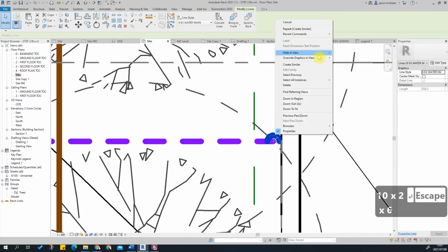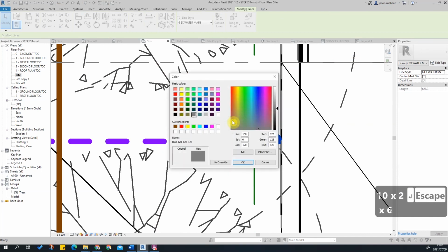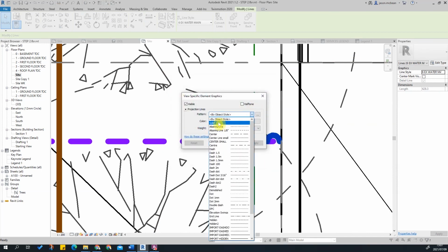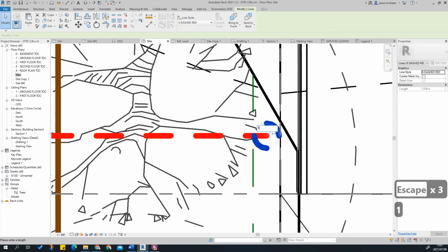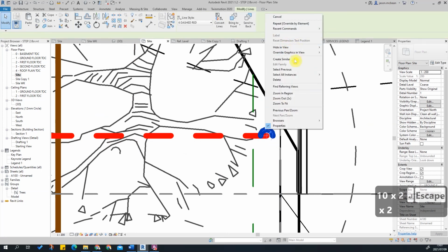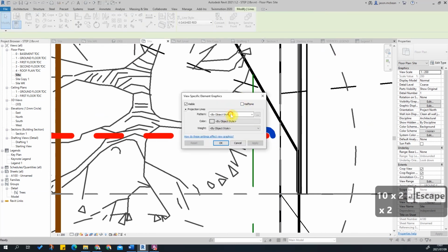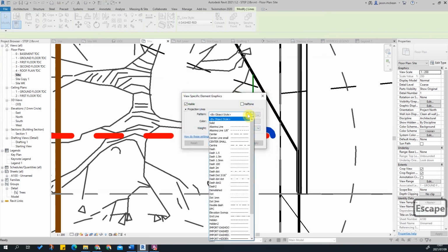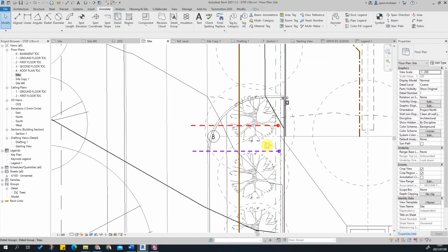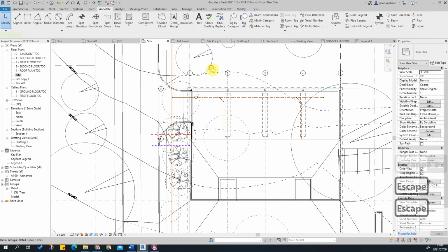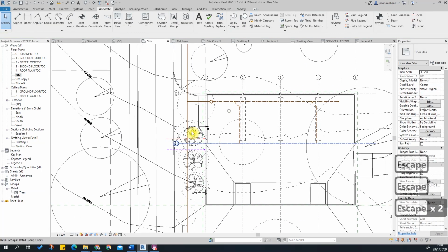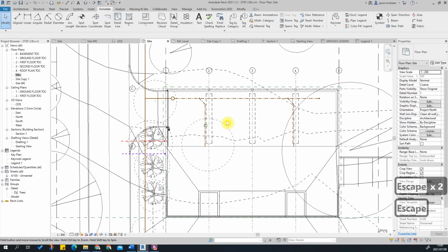You can also override the line, so you can override by element, and you can change it. In this view, you just want this to be a solid line. Here we go. Likewise here, 100. Override element, just in this view, 100. Okay, 100. Okay, and this is only for my site plan, but you can make these a group like we did with the trees. By making this a group as with the trees, that will also help. But by and large, that's how I would add my services. Okay.